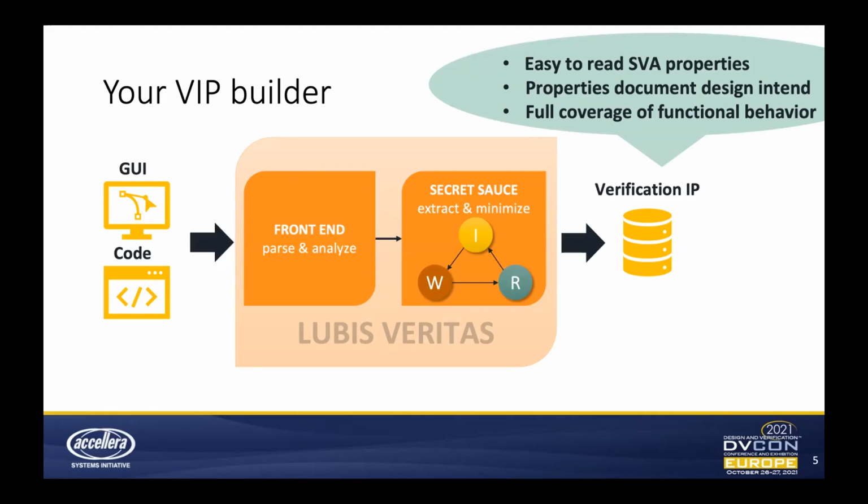Of course, we lose some detail because we have abstract models. And they completely cover the functional behavior of the design, meaning that once we're done with the process, you cannot change a line and change the functionality of the RTL without the verification IP indicating the wrong change and that something goes wrong. That, of course, is a pretty strong statement, because then you can actually go on and refactor your code, search for deadlocks, dead code and unreachable code, or just rename and refactor stuff without being afraid that you break the code.